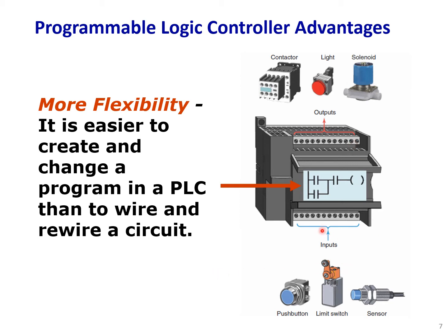So we don't basically touch the hard wiring in a PLC. The inputs and outputs, these are inputs and these are outputs, are, let's say, the same, and all of them are connected to the inputs and outputs ports of the PLC, and if we need to change the logic, we just need to change the program.